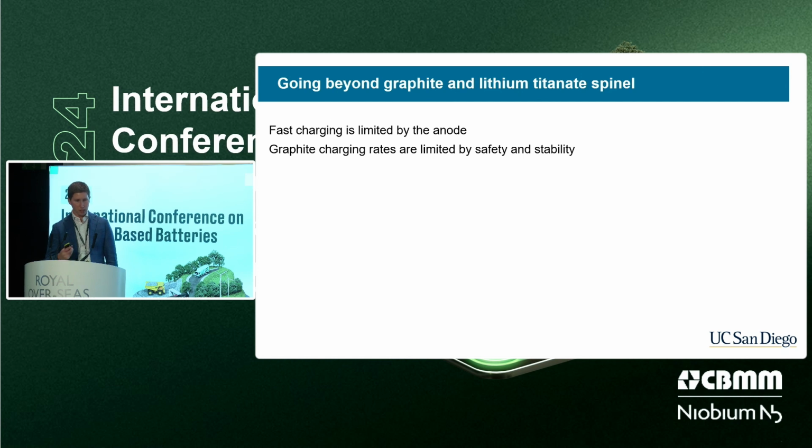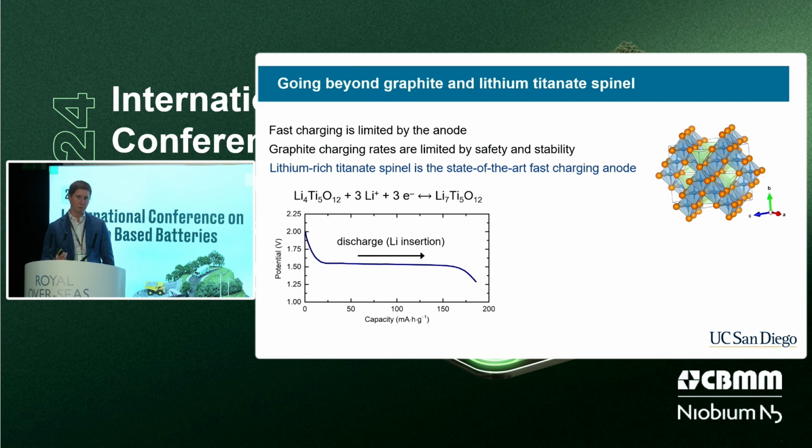And so the challenge with graphite is when you need to have the highest power densities or the highest charging rates, or you need a battery that can operate for 5,000, 10,000, 15,000 cycles, you start to run into these inherent intrinsic thermodynamic limitations of graphite related to the structural stability, the stability of its SEI, and with respect to rate, the ability of graphite to intercalate lithium quickly enough without the possibility of forming dendrites. And so there was a shift there, and that's where the LTO anode really kind of found its home.